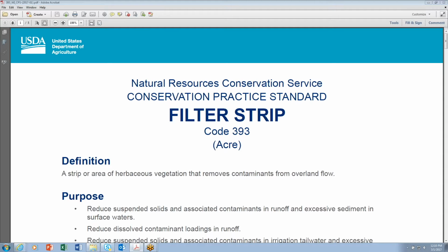And I can tell you that if you are at a tolerable soil loss on your contributing uplands, and that's a tolerable soil loss according to RUSLE2, and your area of filter is at a 1 ton loss, so that's tolerable above it, and then you've got it controlled to 1 ton going off the site, then all of those should last to 10 years.